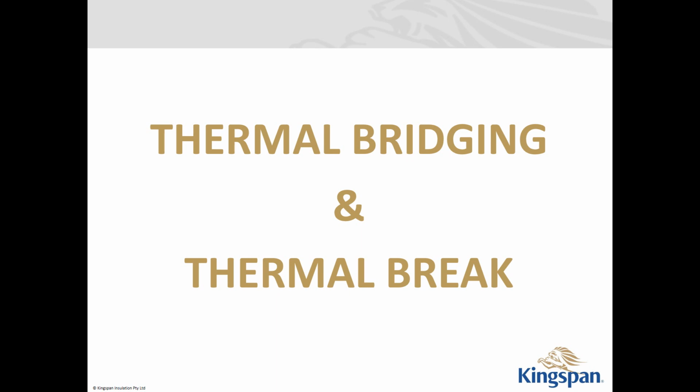So the actual R value was reduced slightly. They then built a steel frame building with the same type of construction: FC sheeting, R2 insulation in between the FC sheeting and the plasterboard in the steel frame. They measured the R value, and the actual R value was an R1.2. So it reduced quite a fair bit, because with the timber construction there was a little bit of heat gain through the passage of the timber, but with the steel construction there was a lot of heat loss through the steel.